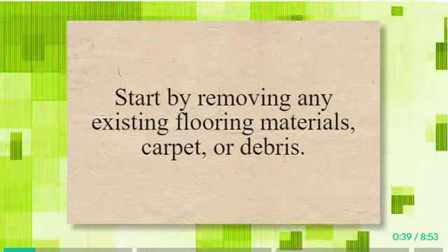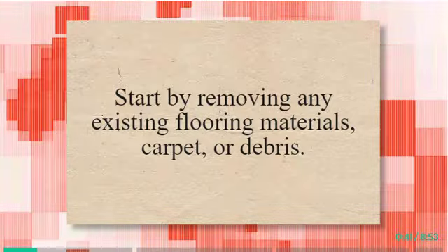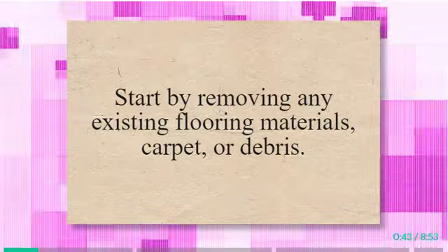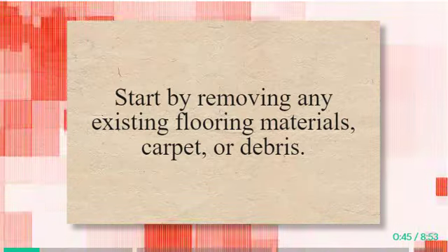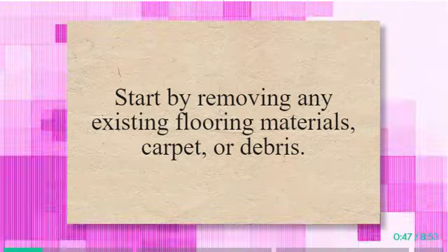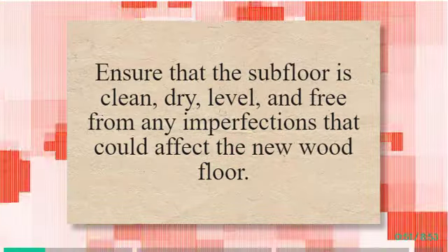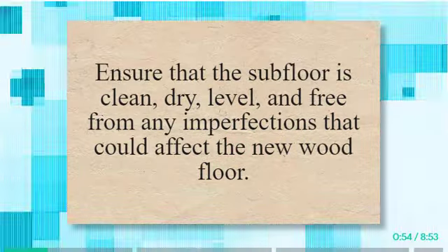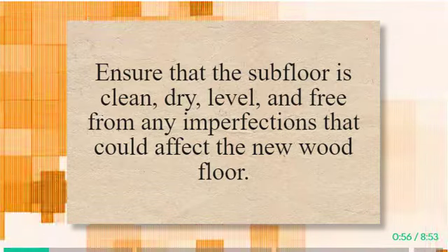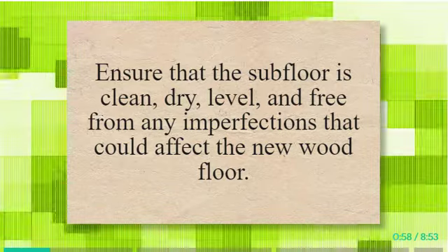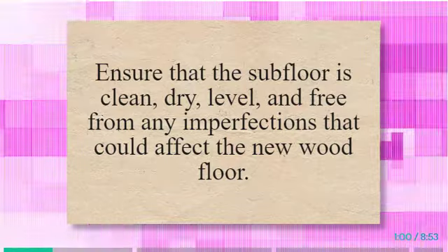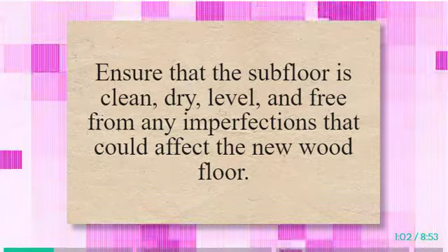Step 2. Prepare the subfloor. A well-prepared subfloor is crucial for a successful wood floor installation. Start by removing any existing flooring materials, carpet, or debris. Check the subfloor for any squeaks or loose boards and repair them as needed. Ensure that the subfloor is clean, dry, level, and free from any imperfections that could affect the new wood floor.